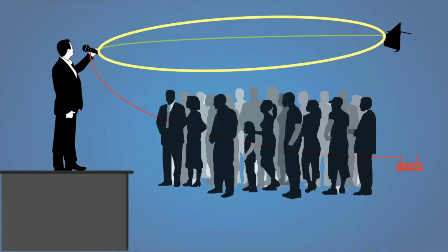Now, if we were to lower that antenna so the top of people's heads actually stuck up inside that yellow ring, the reflections off their head would come into your antenna out of phase. People don't reflect a lot, but if that were the floor, that's why looking at the receiver in the red on the bottom, you are definitely in the Fresnel zone, because the floor is going to bounce up, and everything that bounces off the floor is going to be out of phase into that radio.